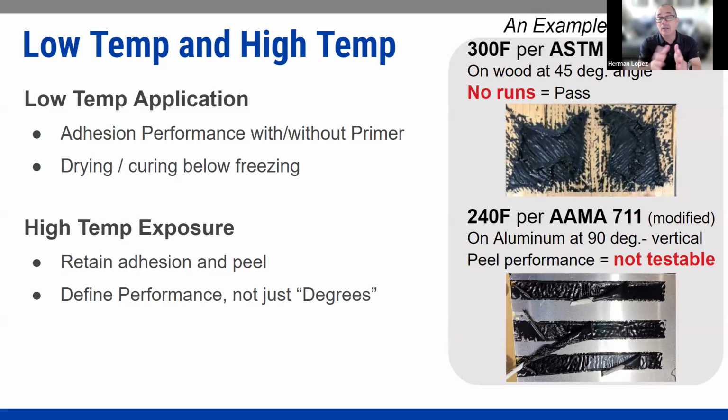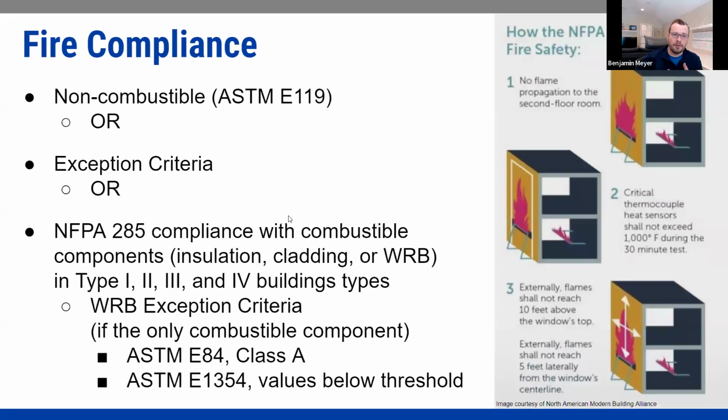Well, what you can't see very clearly in that image is that the HDPE top sheets on both of those disappeared. They shrank away. And in my book, yeah, I suppose it passed this test, but long term, especially behind metal panels, high heat conditions, we have a failure there. We definitely have a problem that's going to show up. So yeah, just being mindful of how you specify, low temp for application, high temp for exposure, just really understanding that. And then I'd kind of let you go into this, Herman, sorry.